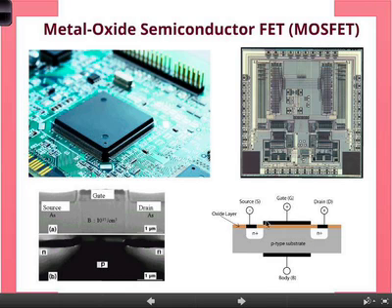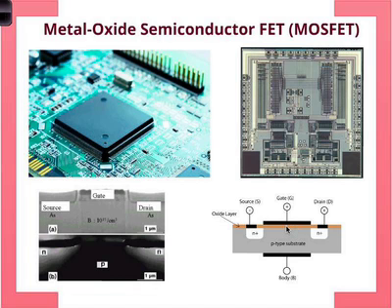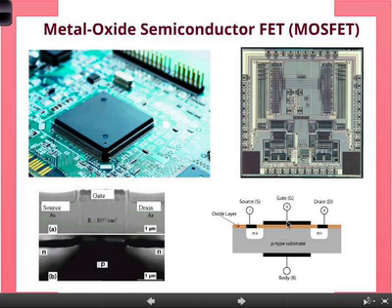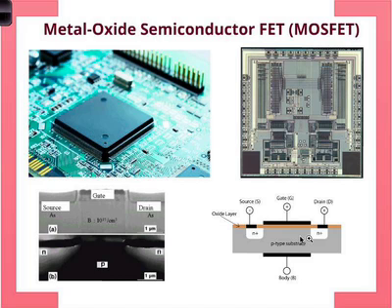Now, what's different is here. You essentially have a P-type substrate, then a thin oxide layer, which is essentially an insulator. When you say oxide, it's silicon oxide, silicon dioxide typically. And then you have a metal contact. Okay, so that's the main difference. And that makes a huge difference in the physics of the operation. Okay, and that's what we're going to understand.